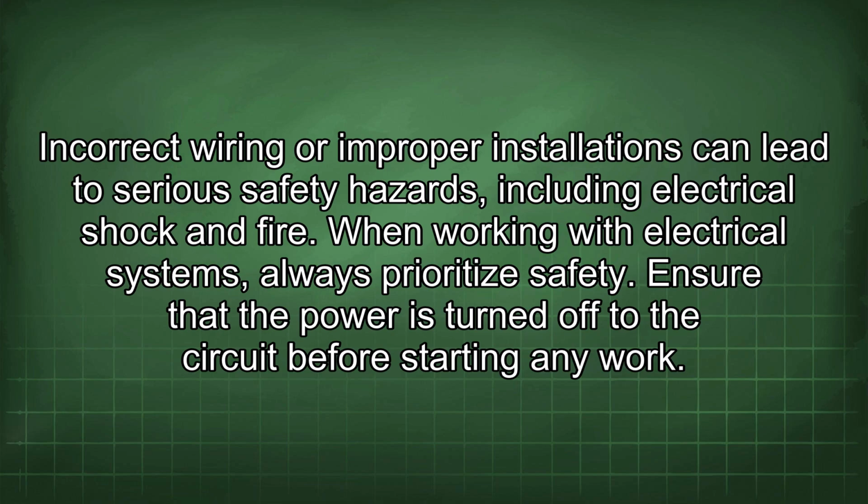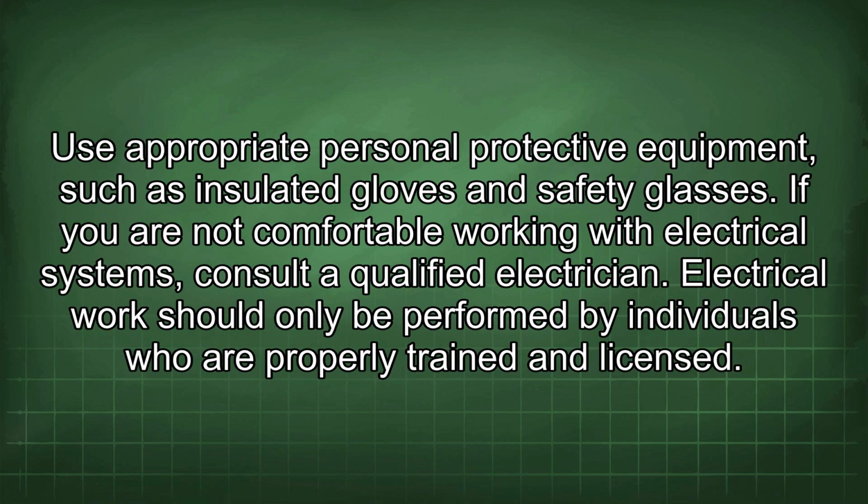When working with electrical systems, always prioritize safety. Ensure that the power is turned off to the circuit before starting any work. Use appropriate personal protective equipment, such as insulated gloves and safety glasses. If you are not comfortable working with electrical systems, consult a qualified electrician. Electrical work should only be performed by individuals who are properly trained and licensed.